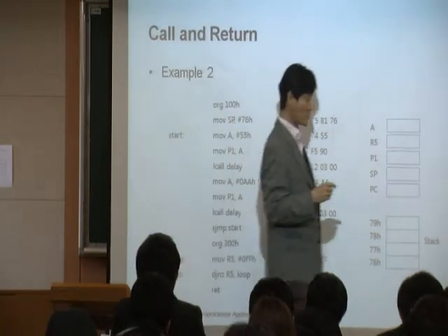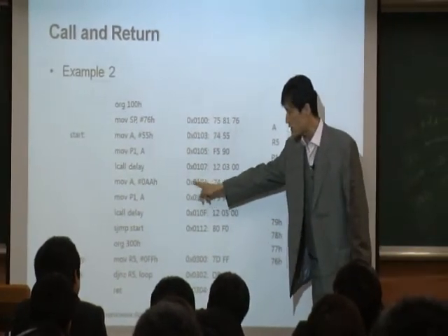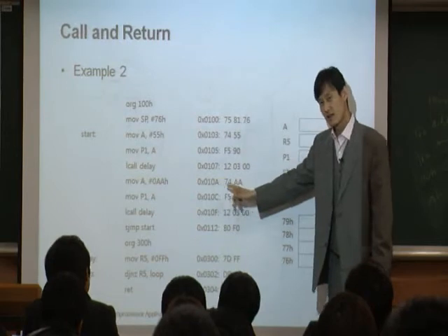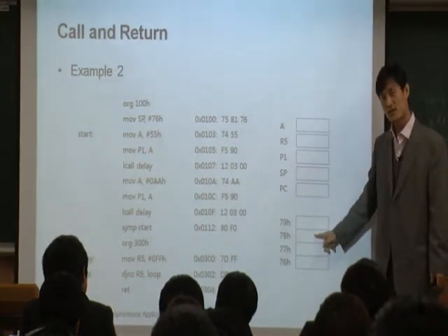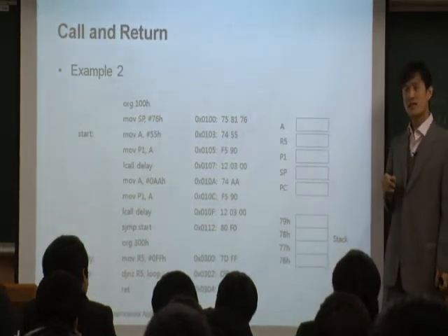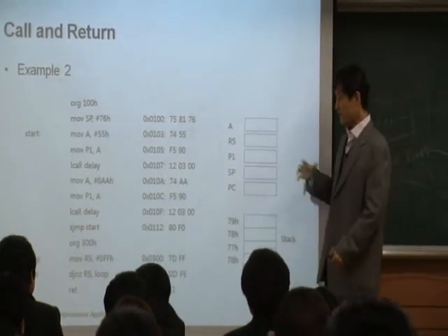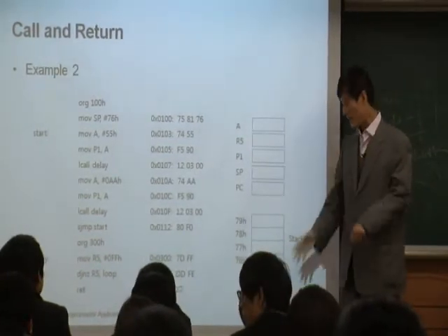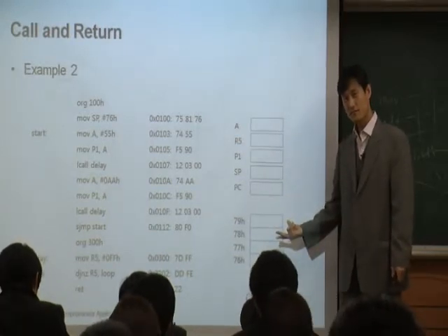Now you may want to ask a question. Since this is a 10A, we have 2 bytes, 01, 0A. Is it like a 01, 0A or 0A, 01? Which one is that? That depends on the endianness. Remember the endianness, like a big endian, little endian? If this processor is big endian, then 01, 0A. Little endian, the other way. Okay?